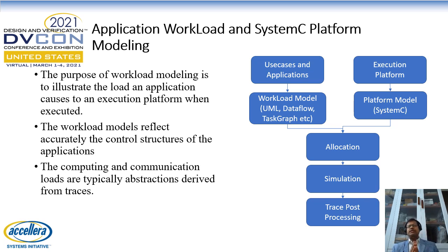So through this presentation, what we are trying to see is, in the field of architecture exploration, how you have performance models, how you have power models, how you can make use of infrastructure like a declarative syntax for wrapping around the functional models into a SystemC kind of a framework, how you can make use of toolkits like the TLM bus toolkit in order to support different bus architectures without having to change the code that you write for a specific bus through convenient sockets.